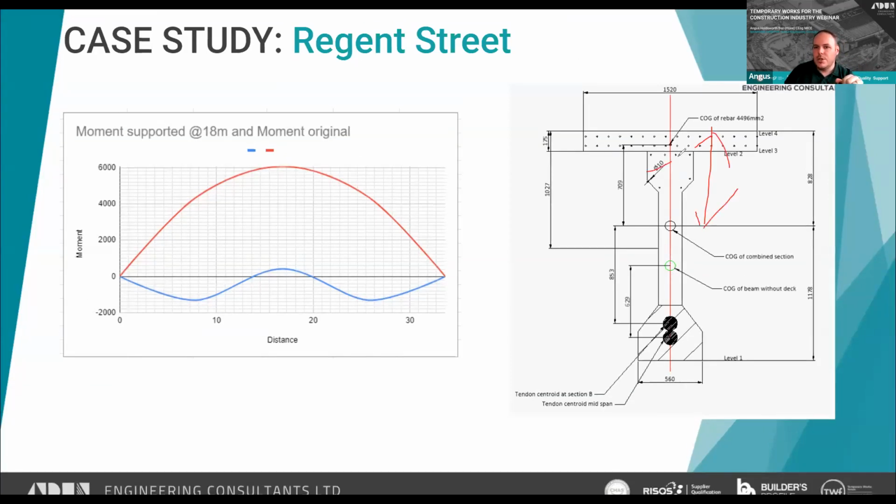You've obviously got compression over this due to the post-tensioning over this here, but this section here, I'm just going to draw in a different colour. What am I doing? I thought there was a rectangle tool. This section here was effectively with zero stress until you start bending it the other way, at which point the reinforcement steel starts picking up the tensile load.